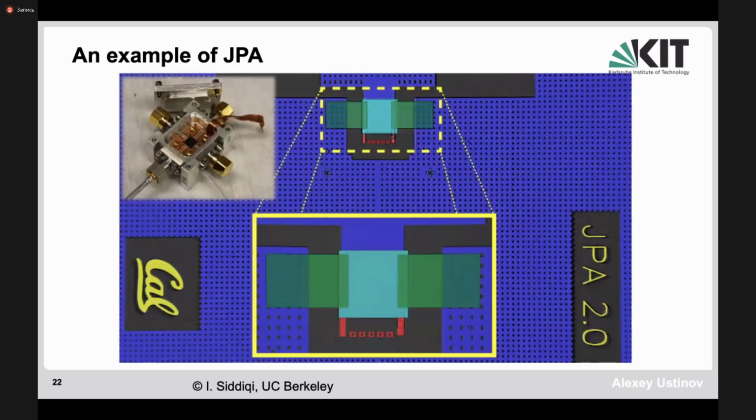Now, how does the parametric amplifier look like? Well, in principle it's just a box which has several ports, and the signal which will be reflected from this amplifier goes in one port, and the signal which you apply as a pump can go in the same port or in a different port. And then there are, of course, some control ports, which can be, for example, a port controlling the Josephson junction plasma frequency, which means the operation frequency of the amplifier.